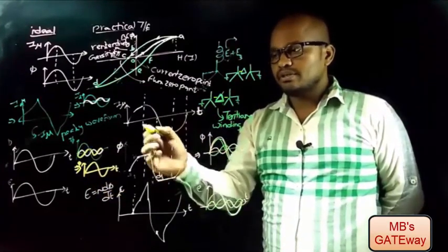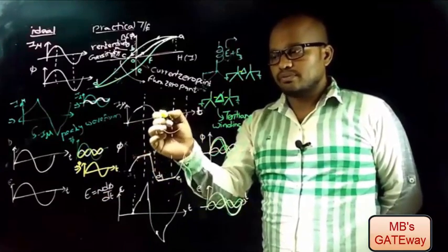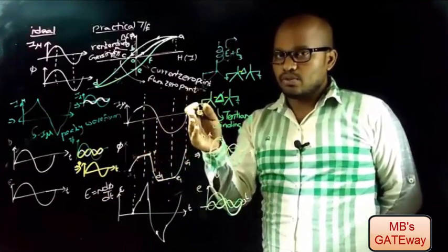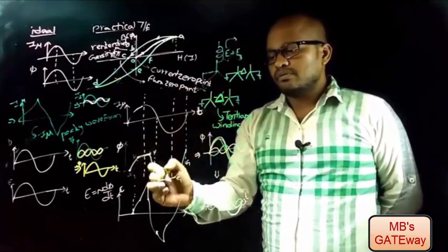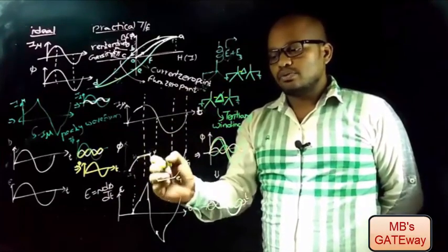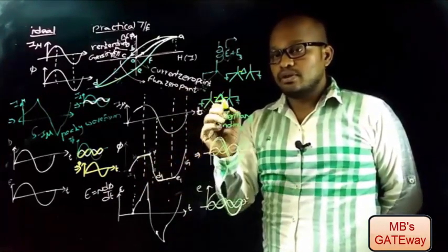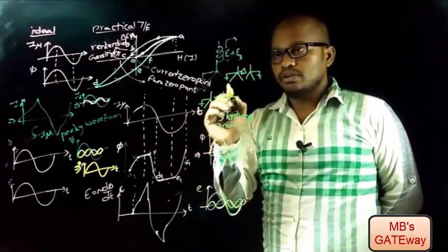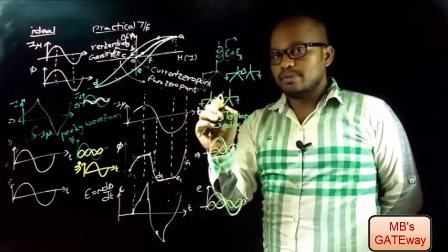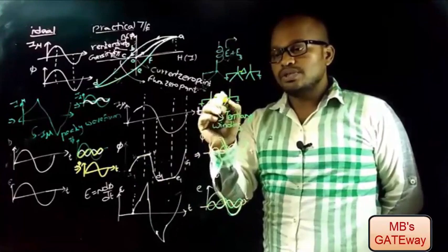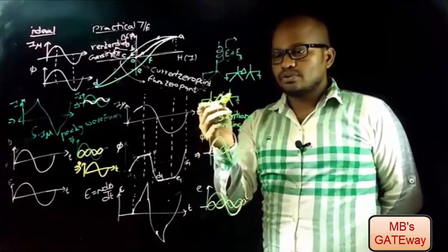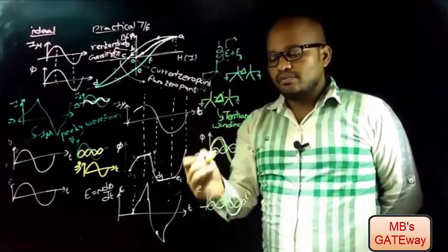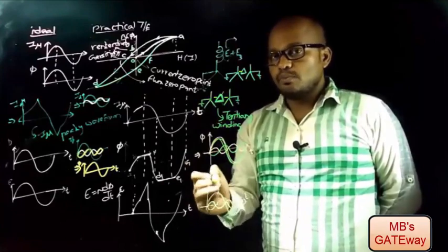And coming to this case, with sinusoidal input to the transformer, the transformer is adding harmonics, because of which flux is non-sinusoidal. And to neutralize these harmonics in transformers, we provide a path to the third order harmonics, that is by making use of a tertiary winding which is delta connected, because of which third order harmonics are reduced, and then we get sinusoidal output EMF.